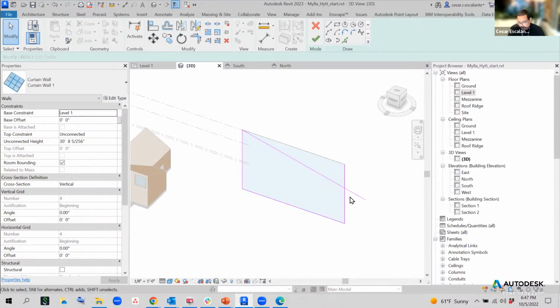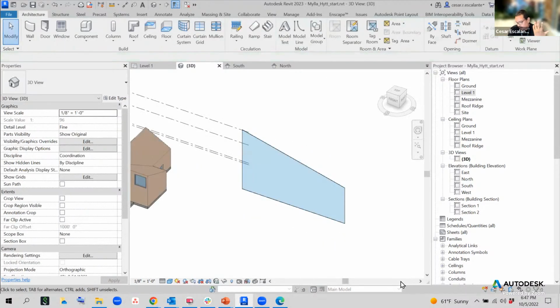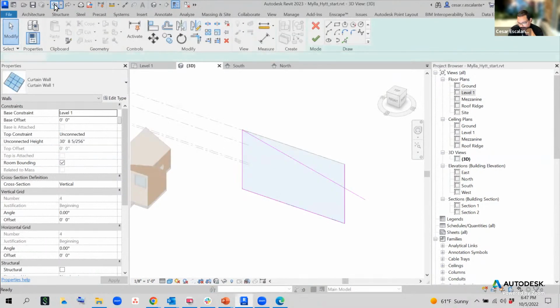They don't need to. I have to clean this using the trim to corner. The rules of sketch mode is no closed loop, no overlapping lines. And then hit the green checkbox. I have a different shape. I'm going to reverse it. I'm going to keep it the way it was. It was a rectangular one.